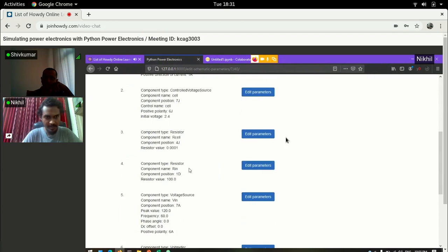In initial resistance, so that we are giving 5 volts. Yeah. So you take it this way. So 5 volts and 2.4 volts is the lowest possible voltage. So that means 2.6 volts. Now with 2.6 volts, you want to restrict your current to 3.2 amperes. So whatever we will decide the rating of the cell, by that much current we want to allow. Yeah. So considering 2.5, we will put 2 ohms of resistance. Okay, that's fine.